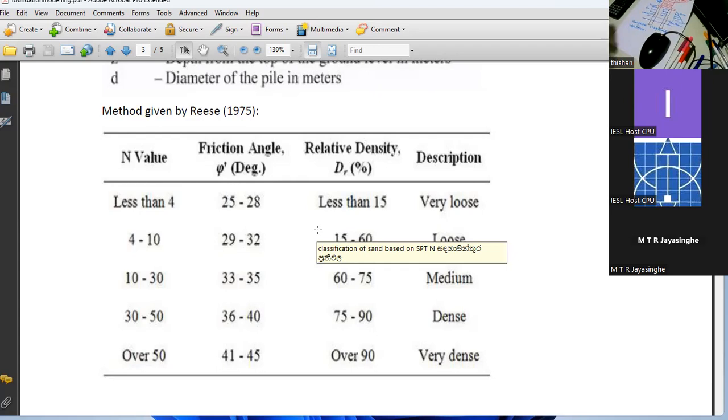If you would like to know how the piles are going to react, then modeling the pile alone is not enough. You have to model the pile and you have to model the soil as well. To model the soil, you need to know the horizontal subgrade reaction, and depending on the type of soil, you can find it.